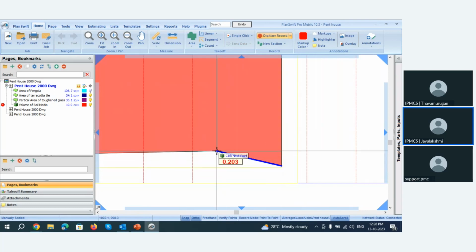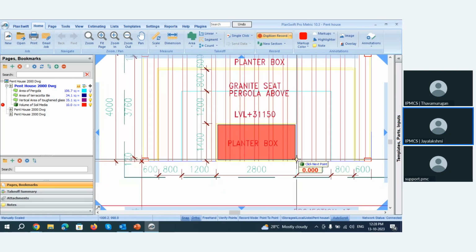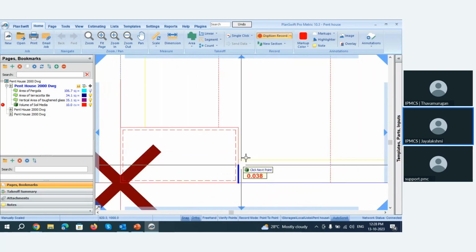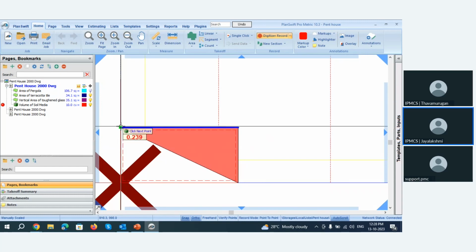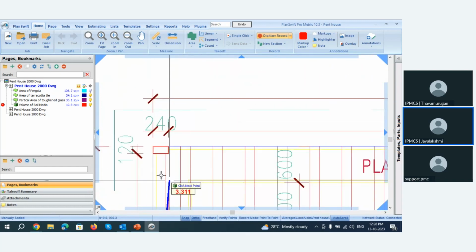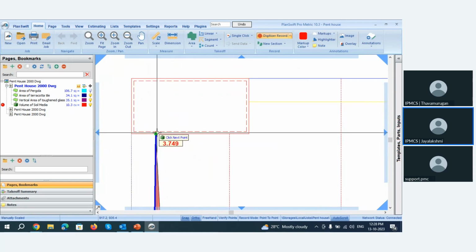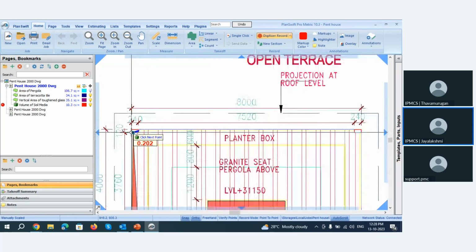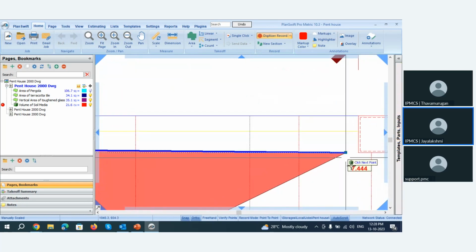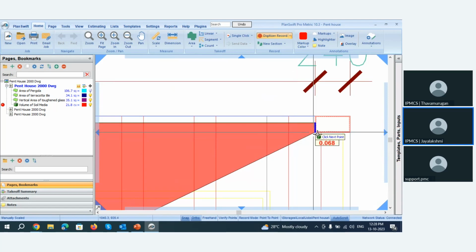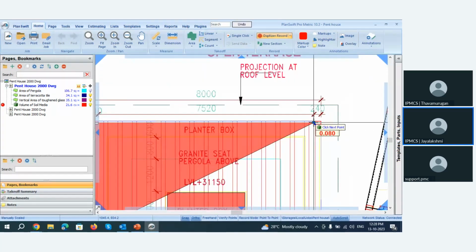And I'll be using N so that I can continue measuring with this planter area. I can pick up the corner points. Since the snap button is activated, it is very easy to pick up the corner points. I'm measuring the inside area for the soil volume.